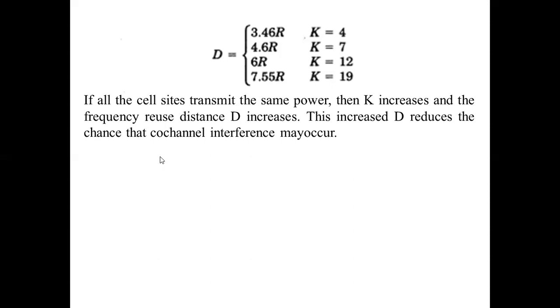If I apply the same principle, spectrum inefficiency is also there if the total number of channels is divided between two network systems serving the same area. So spectrum inefficiency also increases. So we should not have k too large, or too small. Obtaining the smallest number k involves the estimated co-channel interference, and the minimum frequency reuse distance D is to be used to reduce the co-channel interference.